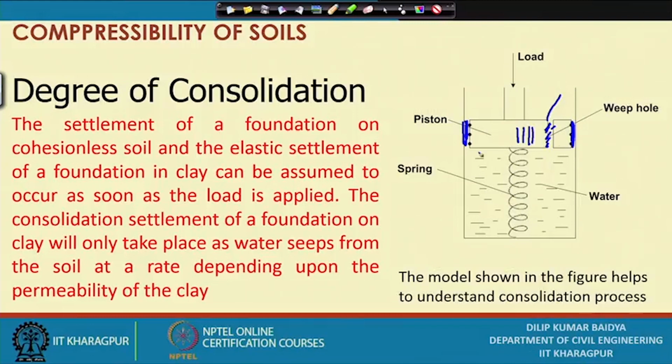So, this is the mechanism, in a similar way, when it is a sealed container, below there is a spring, but if I push the piston, unless water is coming out, the load will not be transferred to the spring. The similar mechanism applies in saturated fine grained soil: if I apply load onto that, unless some amount of water comes out to allow the volume change, this extra load you have applied will not transfer to the soil grain. So, that is the mechanism of consolidation.